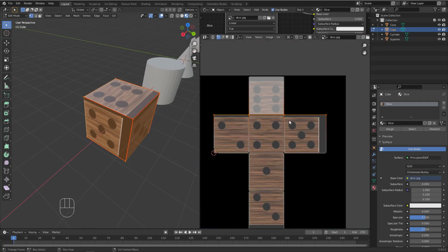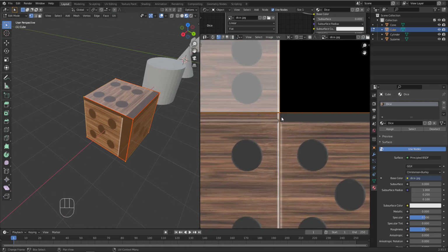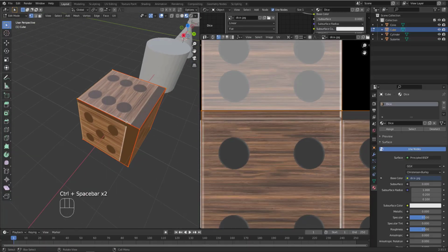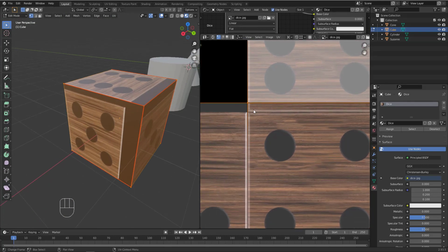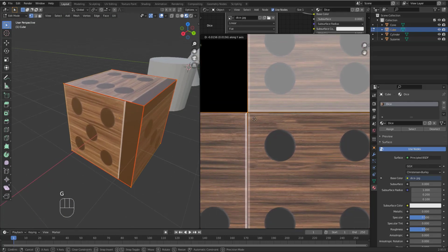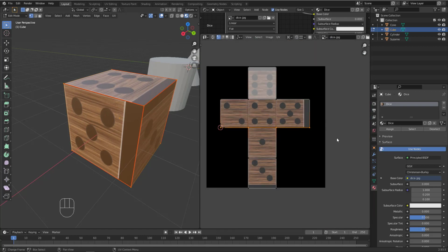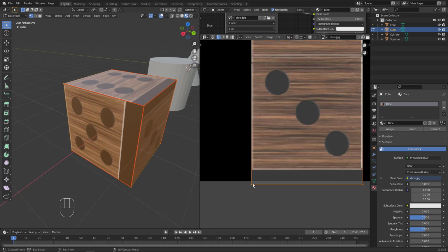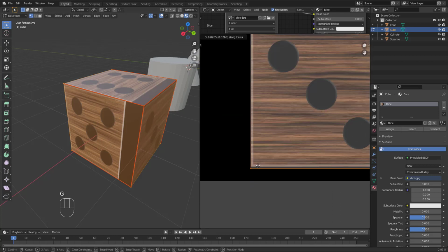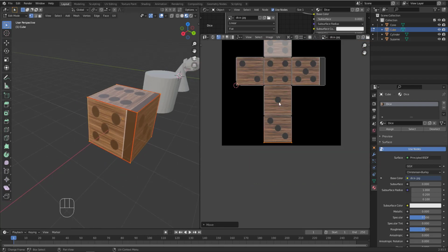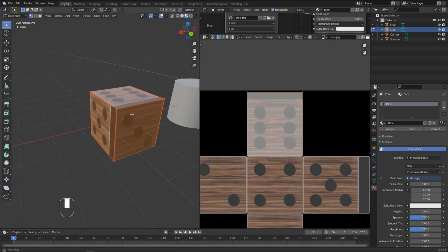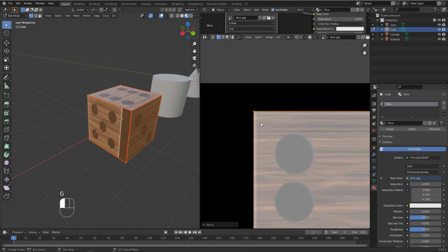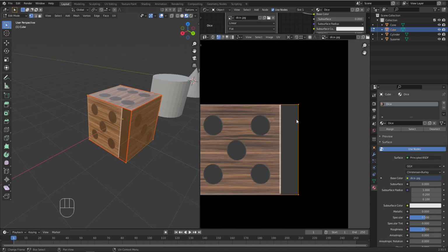And these vertices, I will grab them and move them down, hit G. Let's maximize this, or let's go here because I just need to see the change. Hit G and move those down right here. There we go. And maybe those, no, they are perfect. These vertices, I just need to push them just a little bit here, and there we're going to correct. And what else? We have this side, we need to correct it, grab them, hit G and move it. Cool. And this one as well. Hit G and move it.